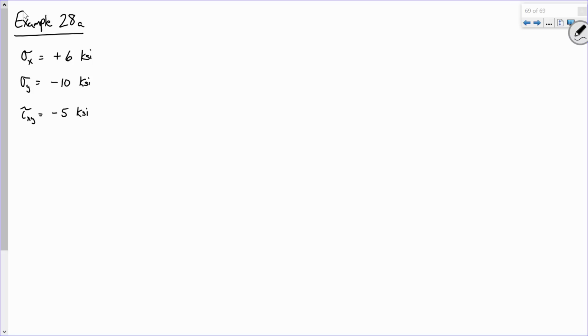Okay. So the first thing we're going to do is find the angle of rotation. Now this is a 3, 4, 5 triangle, so you could argue, well, I don't really need it because I know what the cosine and the sine are. It's just the 3/5 and the 4/5. But ultimately, we're going to be taking the cosine of 2 theta and the sine of 2 theta.